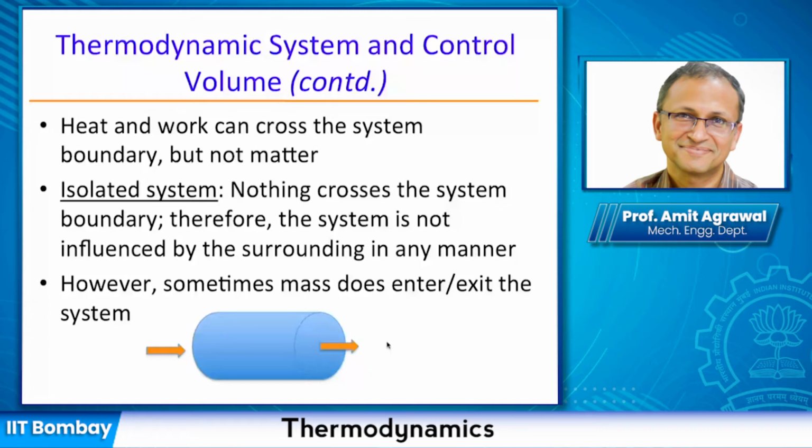Therefore, what I will rather do is define a segment of this pipe and say that this is my control volume. So this segment shown here is my control volume. I am going to apply all my principles of motion, essentially my laws of mechanics, to this limited volume that I'm looking at.